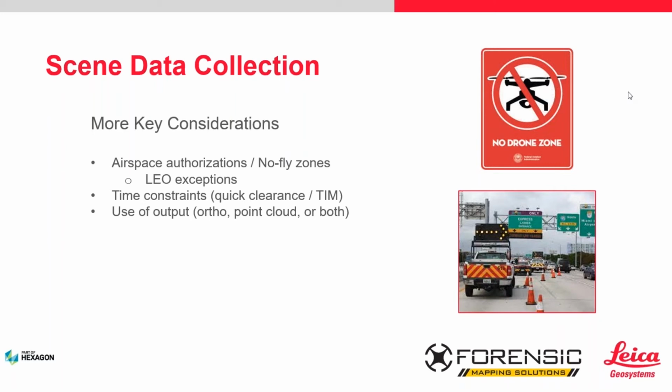And then finally, as far as airspace, you have the issue with the drones themselves. DJI, which is what most people fly, has no-fly zones, or geofence no-fly zones. That has nothing to do with the FAA. It has to do with the drone itself, where they're saying that it's not a good place to be flying. It's near an airport, it's in controlled airspace, and you won't even be able to power your drone up.